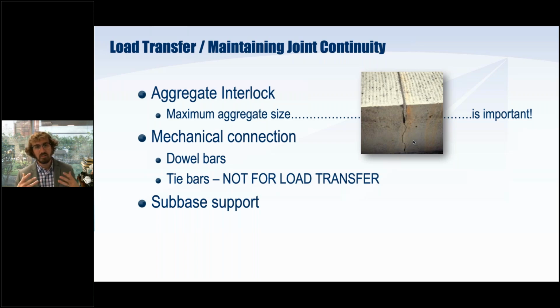Those are meant to be long-term load transfer devices, really meant for transferring that load from one slab to the next, especially when we have heavily loaded trucks. I always like to mention that tie bars, while we use them a lot in our longitudinal joints, are not really there for load transfer.